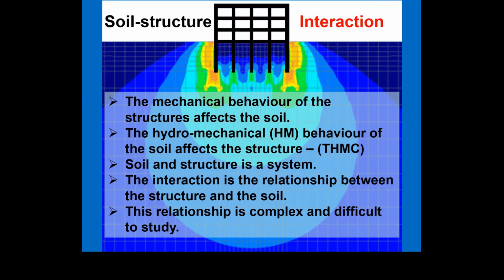You know that there is a principle called the effective stress that is especially important in soils. This is because this principle covers the hydromechanical behavior, as we say in computational mechanics. So when we deal with soils, it's a little bit more complex because we are not talking about the mechanical interaction between forces and deformation in our material, but the hydromechanical, because water has a role to play, which is very important.